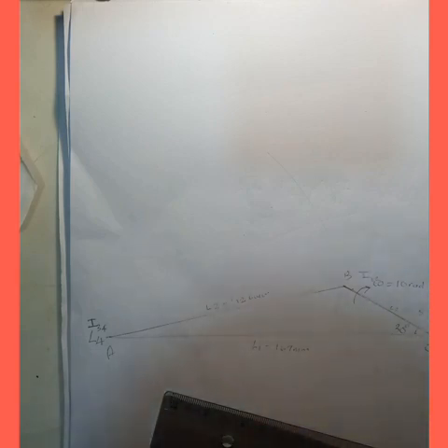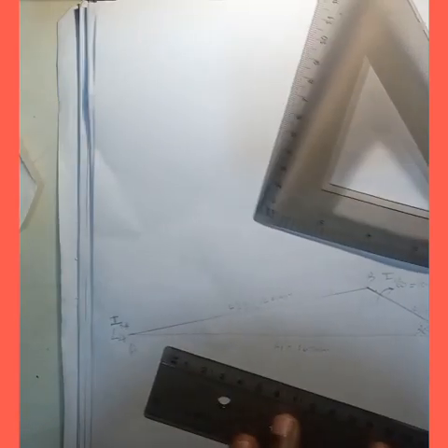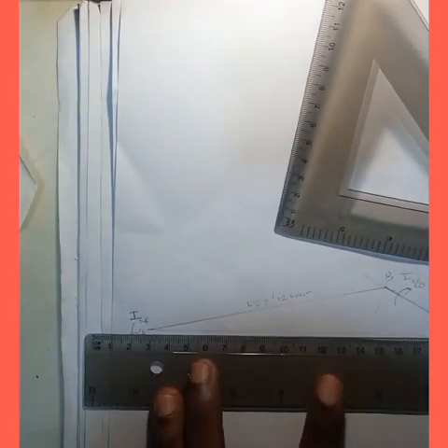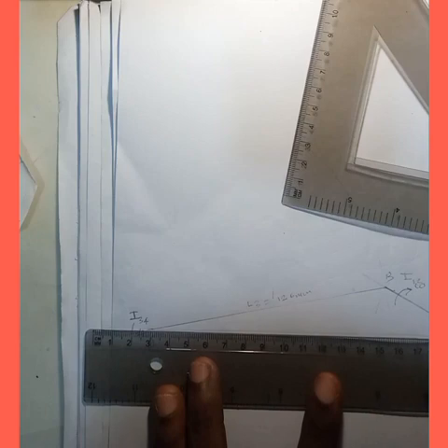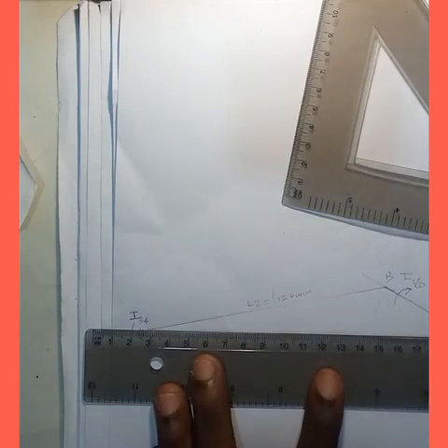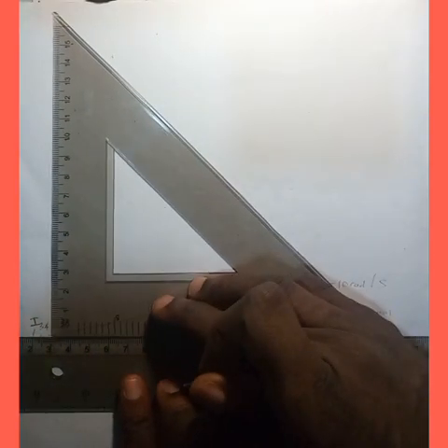And for you to get that I14 infinity, you only need to take a line that is perpendicular to your link 1. Okay, so consider this line. First press your ruler like this and then get a perpendicular line to it.